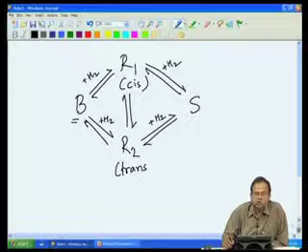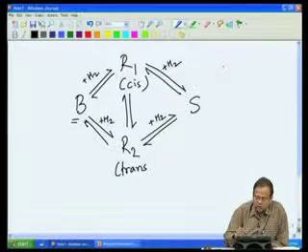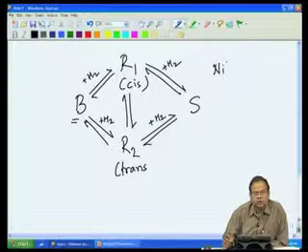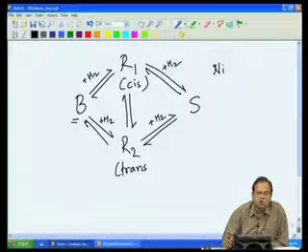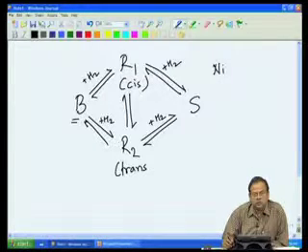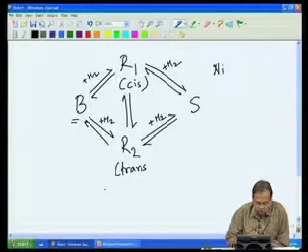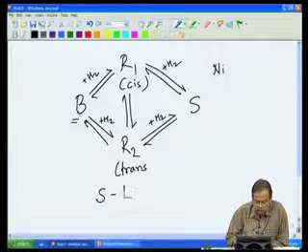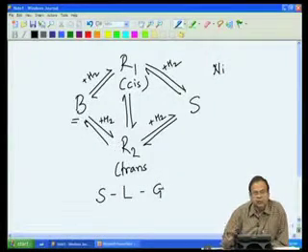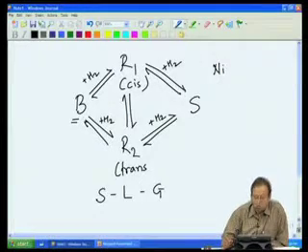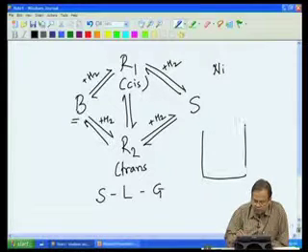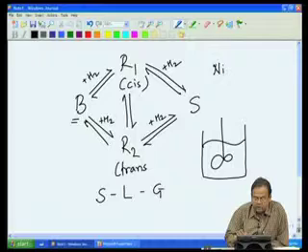Now, I also mentioned that this reaction takes place in presence of catalyst, and Raney nickel or nickel in micron size particles is often used as the catalyst. So, design of this reactor therefore involves looking at a solid, liquid and gas reactor, and slurry reactors are most commonly used, or in other words we have a stirred tank reactor in which let us say oil is present, a batch reactor we are talking about.